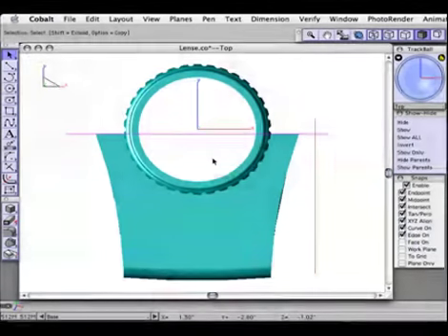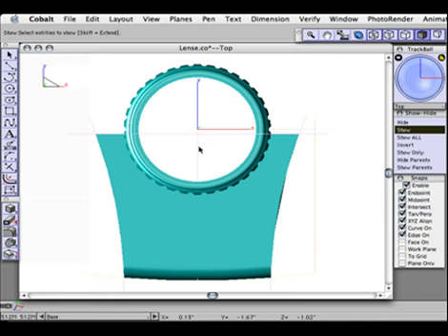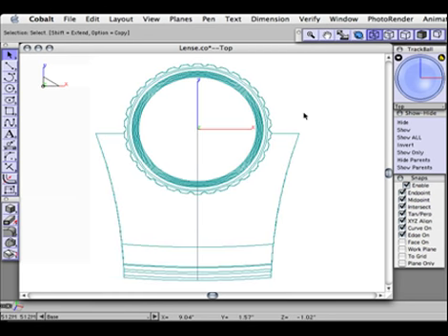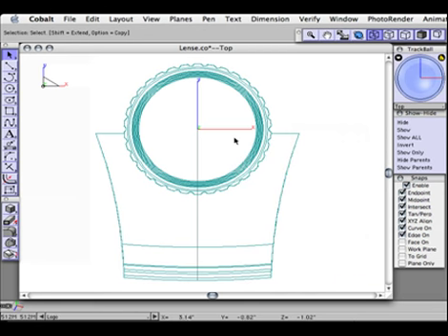The Ashlar-Vellum solid modeling programs support the Illustrator format as an import option. So what we're going to do is show only our solid part. Then I'm going to show that line that draws down the center point of our part. I'm going to switch over to wireframe viewing mode. Then I'm going to create a new layer. And this time I'm going to call this layer Logo. And I'm also going to click to make this layer the active layer. This way when I import my logo, it'll go to this layer.